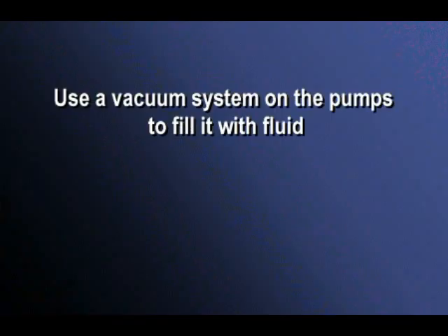Here is an alternative method of priming pumps with negative suction head. Close the discharge valve. Open the inlet valve. Start the pump with a dry casing. Open the vacuum valves to pull air out of the pump casing and draw water through the intake. As the water fills the pump casing from the intake, motor amperage will increase. At a predetermined amperage draw, the discharge valve is opened. Vacuum valves are closed and the pump is operational.